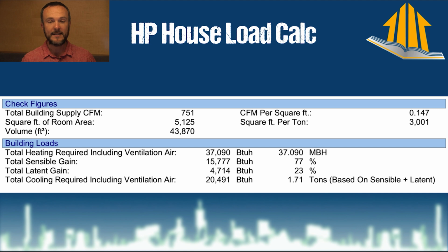In fact, that's written into the standards. So when you have a 16-foot high ceiling, it's totally different on the volume. So the volume is 43,870, which is on the nose what my actual volume is from my 3D model. That's good. The other thing that goes into the square footage here is my crawl space, which I don't count into my square footage of my house because it's a 4-foot crawl space. It's basically a mini basement. It's totally enclosed inside the house, insulated. It's going to be the same temperature and relative humidity as outside, but it has no windows, which obviously is a big benefit for it.